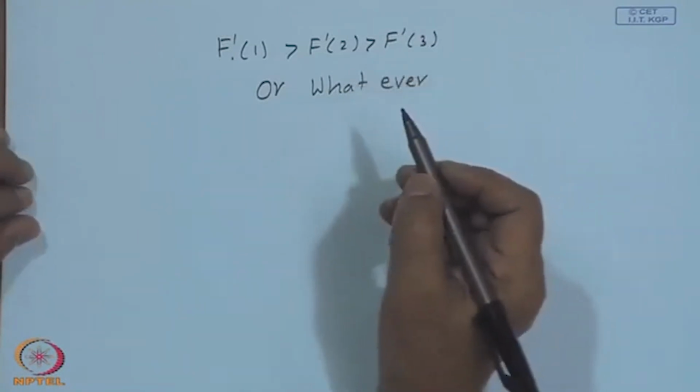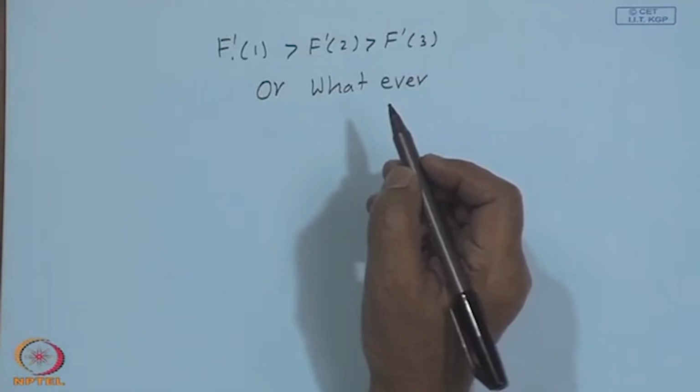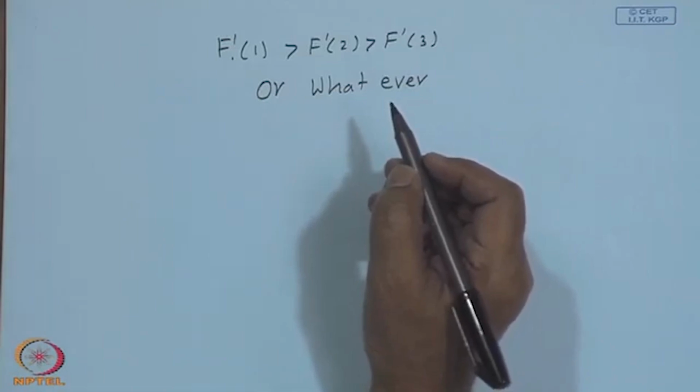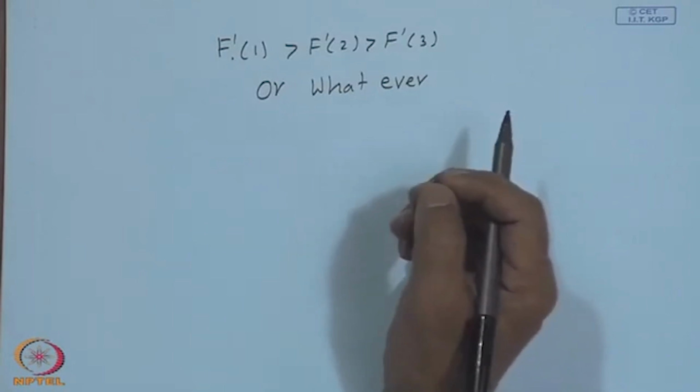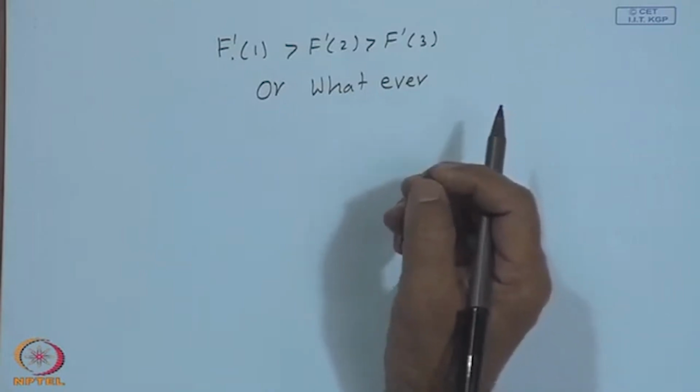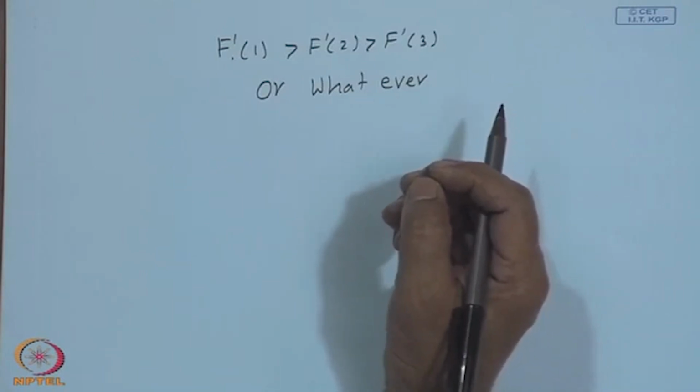Or else one can take a particular material, thickness delta and W and U L, and compute these numbers for the fin efficiency and the collector efficiency factor, and find out which one is better.